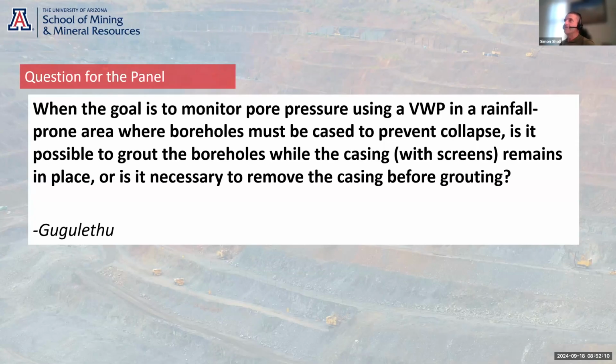It's all about integrity. What you have to have is grout that joins the bottom of the VWP sensor, where you've got the filter, and that piece of grout has to have contact with your formation. That's the critical aspect of the VWP install.